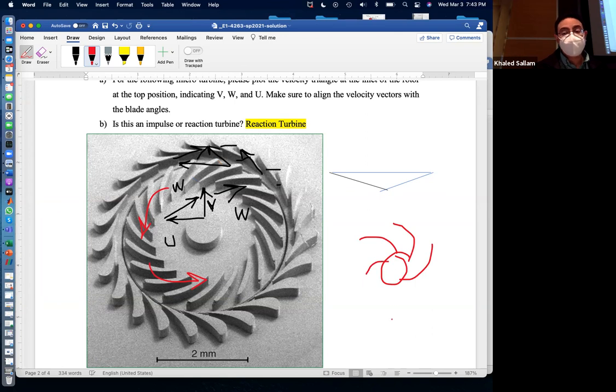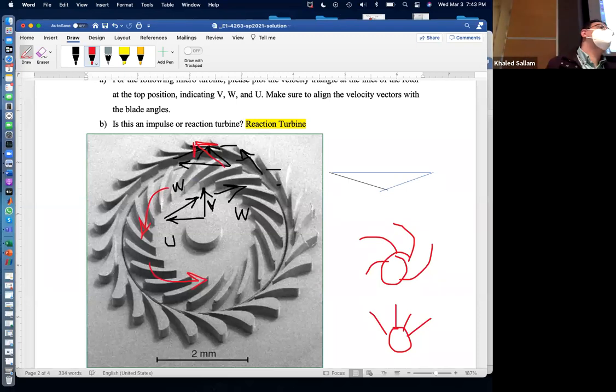Okay? And of course, there is the radial kind, which is more common, right? All of them will always have a V. Don't make any mistake about this. V will always have to be in the direction of rotation. V2 at the exit, you are leaving a rotating compressor or rotating rotor. You have to leave with that twist.